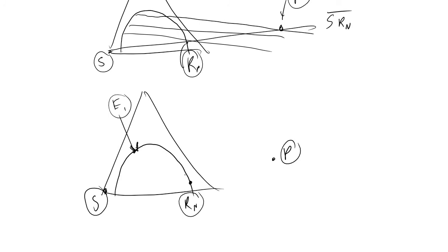What we know happens within our tray n is we have reached some kind of two-phase equilibrium between our carrier phase and our solvent phase, and the tie lines tell us what these equilibrium compositions are. So what we will pretend in this example is that we will have some kind of tie line.